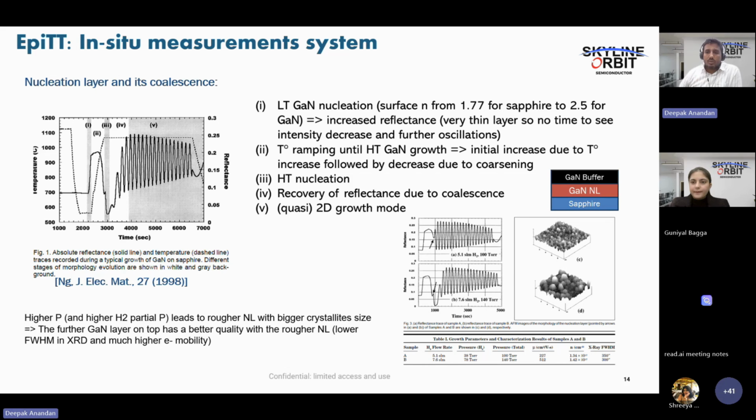And if you ask how gallium nitride will perform in terms of durability compared to others, the major problem with gallium nitride devices is the reliability issue, because as I mentioned earlier, there is still investigation going on into the real source of electrons for the 2DEG. It means there are a lot of defects that need to be addressed. They can be from the buffer, the barrier layer, or the surface.